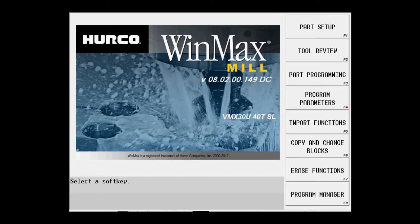Let's program the print Intro 12 from your packet. We have several pieces of geometry that we're going to be programming here: some circles, frames, a couple of holes blocks, one using locations, one using bolt circle. And we have a large slot that we want to create using a mill frame with corner radiuses.